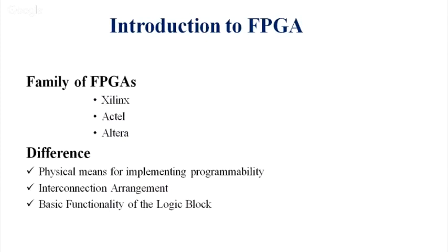Now, what are the families of FPGA? There are several families available in the market like Xilinx, Actel, and Altera. I am working on Xilinx, the Spartan kit given by Xilinx. Now, what is the basic difference between the products of these companies, Xilinx, Actel, and Altera? Basically, they differ in the physical means for implementing programmability, their interconnection arrangement, and the functionality of the logic blocks.